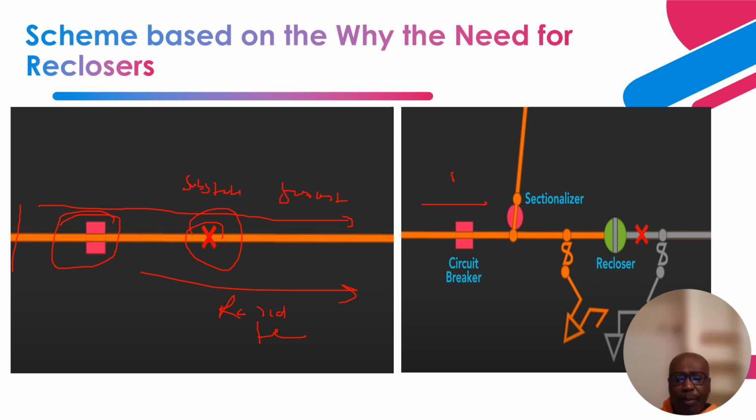The next picture shows us the circuit breaker and a recloser that is dedicated to 2 pad-mounted transformers that are connected, and you have an open loop over here. Like I indicated, if a fault should occur over here, the circuit breaker is not going to trip.